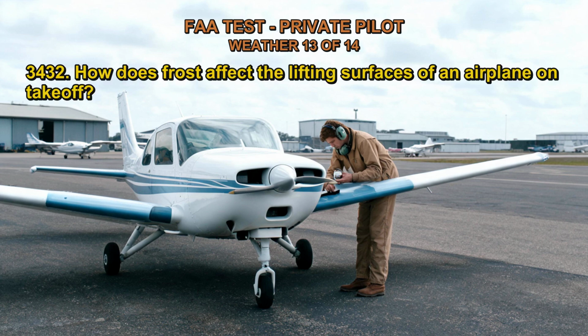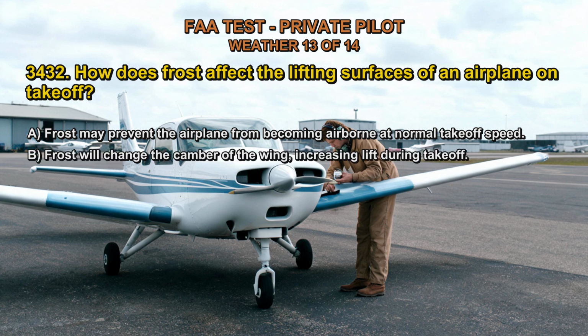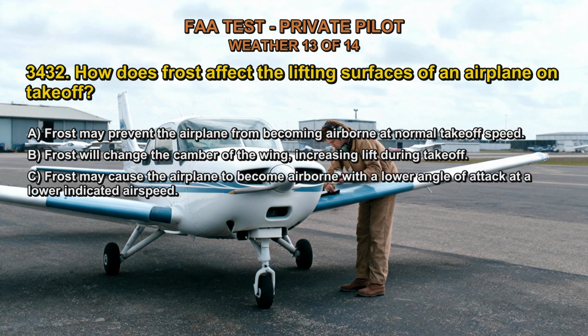3432. How does frost affect the lifting surfaces of an airplane on takeoff? A. Frost may prevent the airplane from becoming airborne at normal takeoff speed. B. Frost will change the camber of the wing, increasing lift during takeoff. C. Frost may cause the airplane to become airborne with a lower angle of attack at a lower indicated airspeed. The correct answer is A.